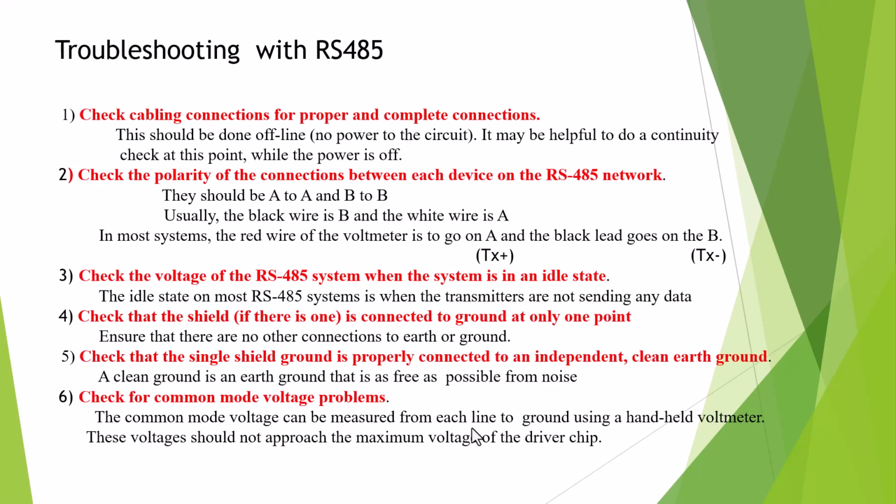Okay, troubleshooting. If you work with RS485, you should know how to troubleshoot RS485. If you do a technician job, sometimes RS485 is not working, so you should check the cable connection for proper and complete connection. So this should be checked.